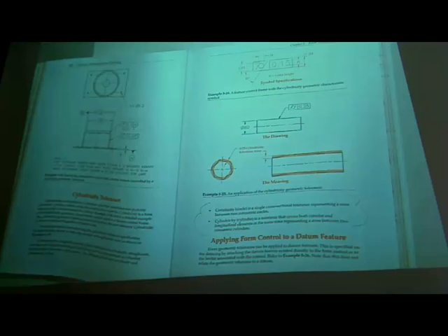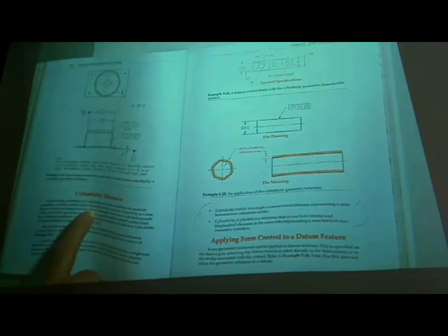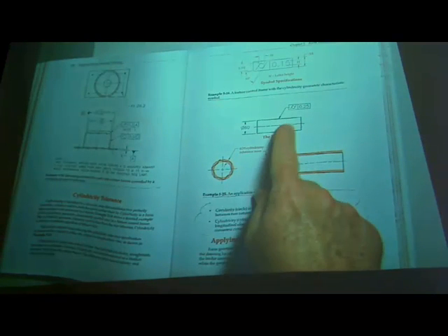And again, it is not referenced to a datum, but it may be used as part of a datum device or datum setup. It doesn't reference a datum, but a datum references it. A datum can be created from it. Okay, it's like this pen. This is a pen, and we're going to use this as part of our datum. And that pen may have certain cylindricity controls on it.